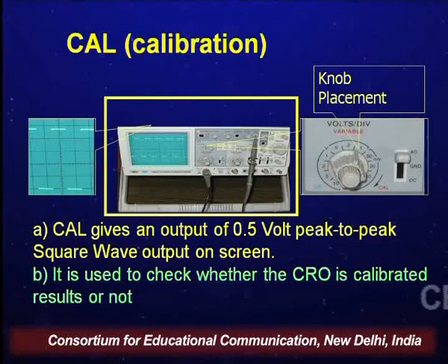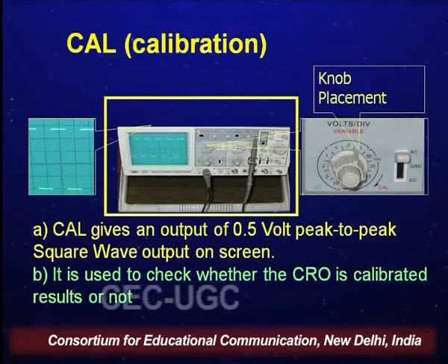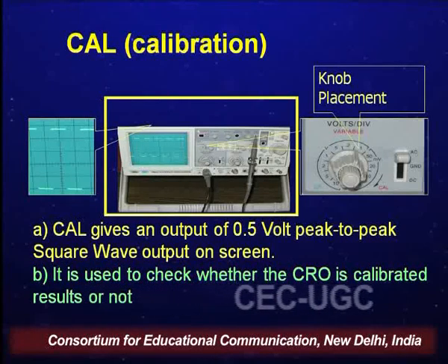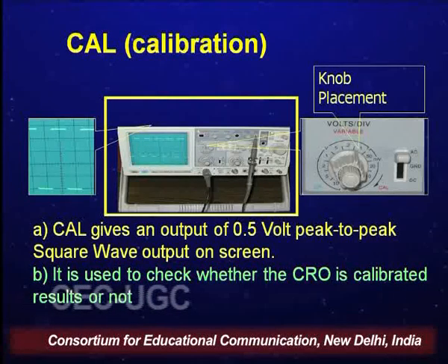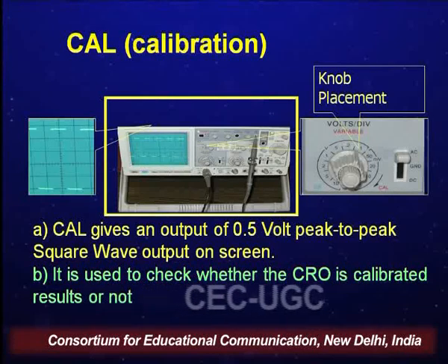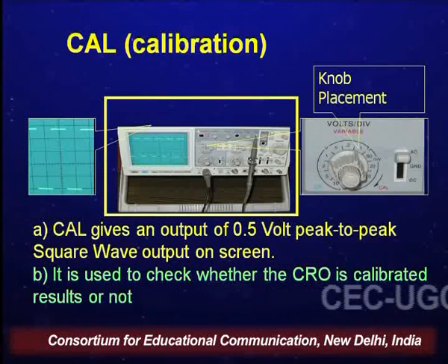It can be a button, it can be a knob, and there is the word CAL written on top of it. You have to always ensure that this CAL button is clicked in the right place to ensure that the waveform that you get to see is actually calibrated.